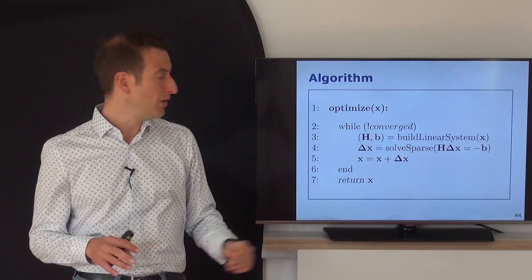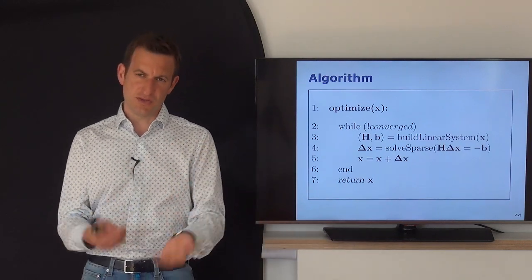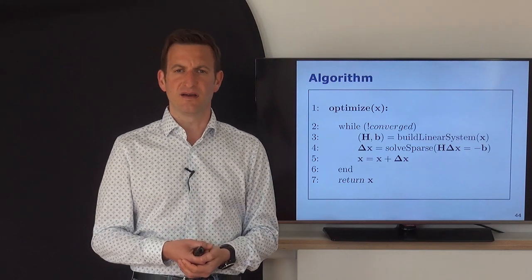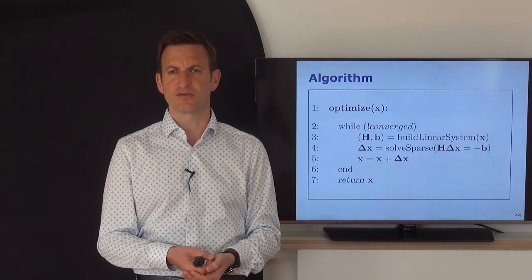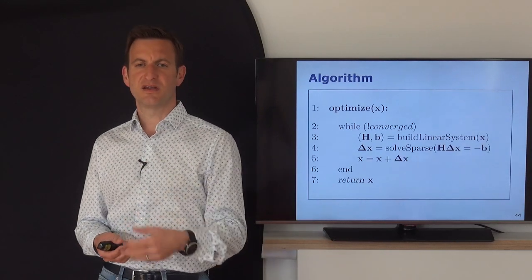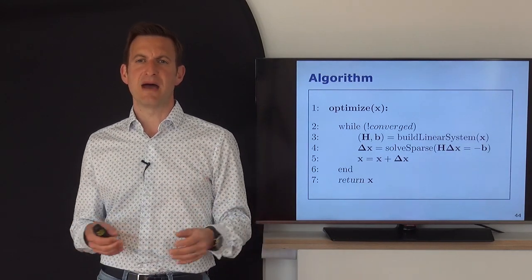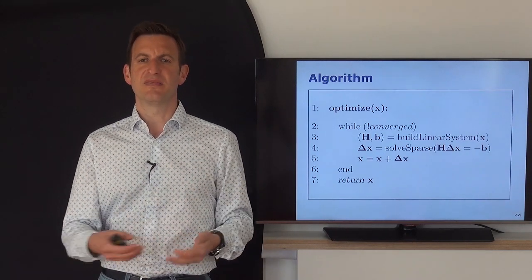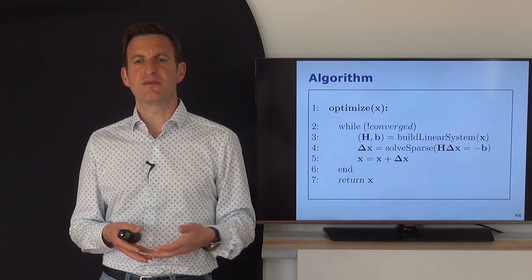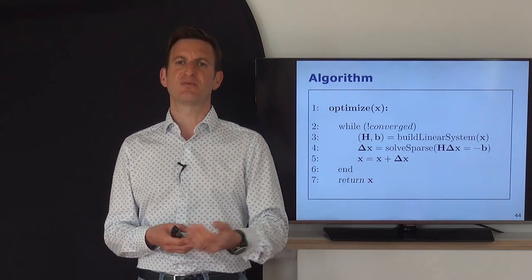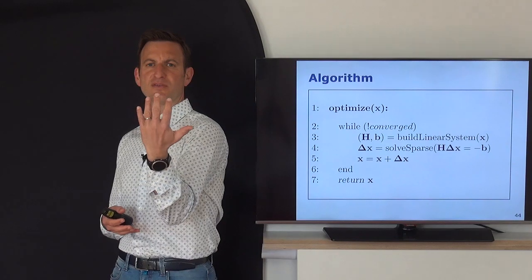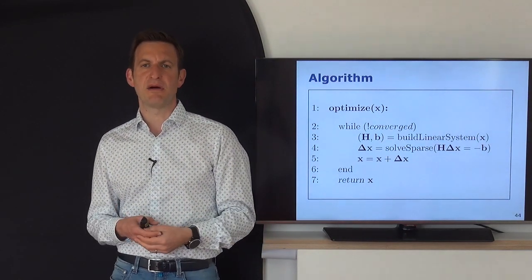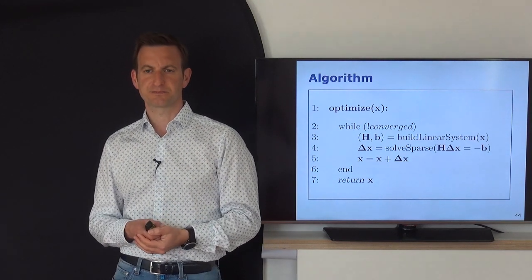And then I come up with a new configuration x, which is now the new configuration of my graph, which minimized the sum of the squared errors over all constraints. And this is then the result that you can use in order to build the map of your environment. Just take the poses as they are, the best estimate you have, and then basically run a mapping procedure based on those poses and build a map of the environment. That's what's typically done. So you correct the poses first and then use the poses for your mapping algorithm, which is not a SLAM algorithm anymore. And then you're done.